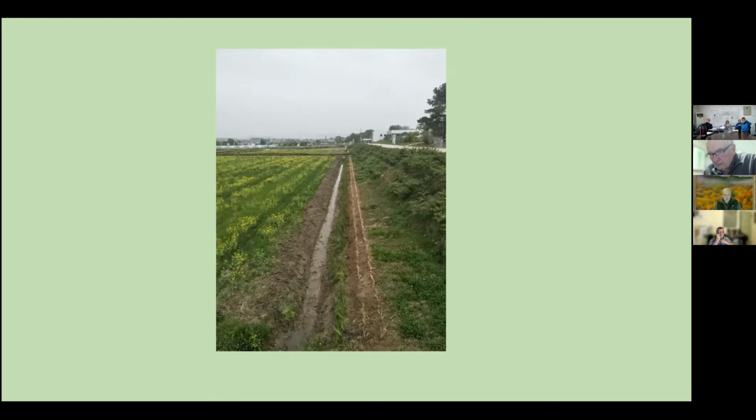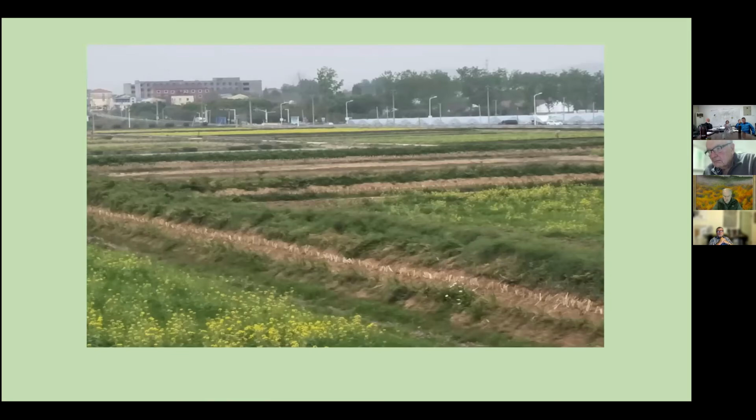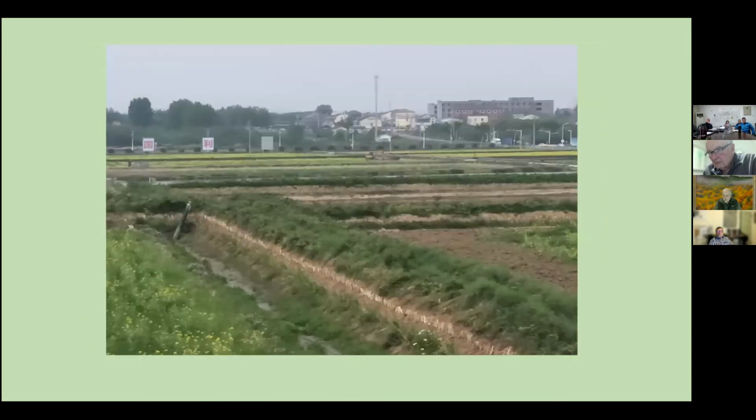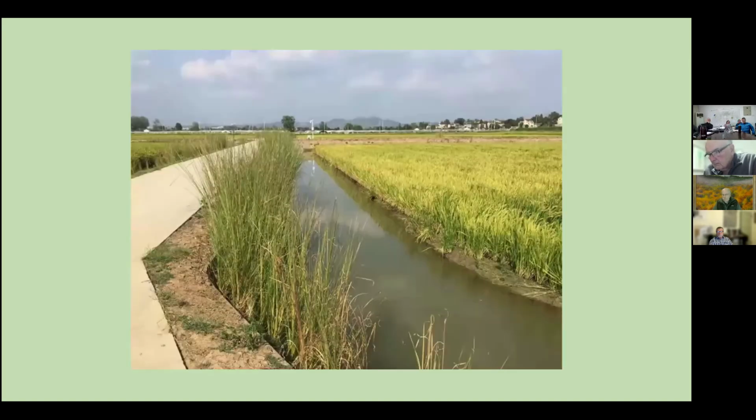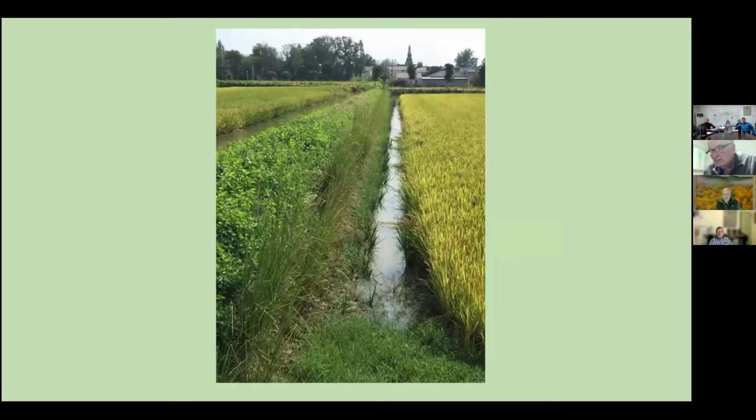Here we plant the Vetiver along the ditches around the rice plants. Now this one, we plant some Vetiver around the ditches, on the slope of the ditches, to protect the ditch sides. And at the same time, this Vetiver has some borer control functions. Yeah, this one has the same functions. Now I just show some results. Yeah, here, you know, the Vetiver will build up. Within two years, it will build up around the rice lands, rice fields. Yeah, some Vetiver along the ditch sides, the slopes. And then they can protect the slopes of ditches or irrigation systems.